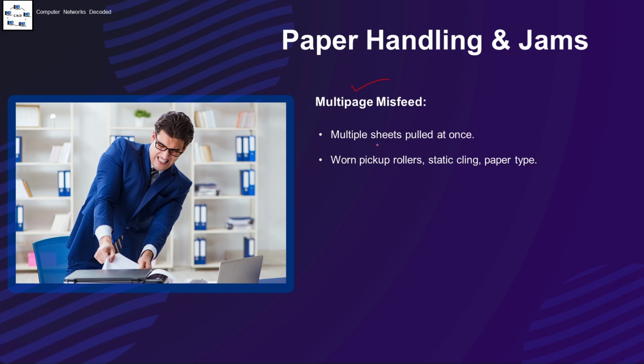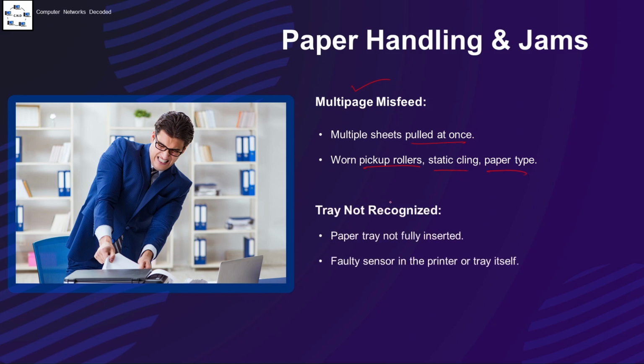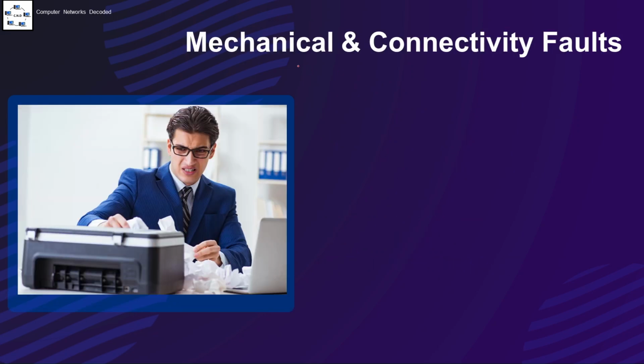Multi-page misfeed, so multiple sheets pulled at once, may be due to worn pickup rollers or static and paper type. Tray not recognized: the paper tray is not fully inserted, or there is a faulty sensor in the printer or tray itself.